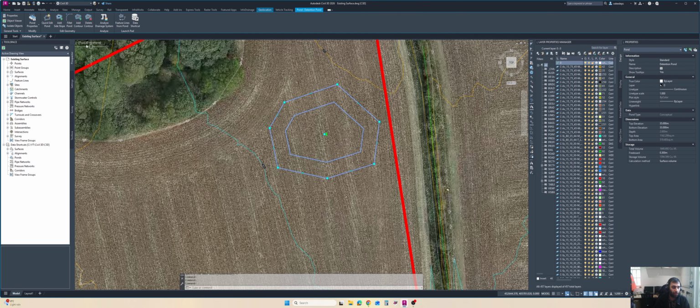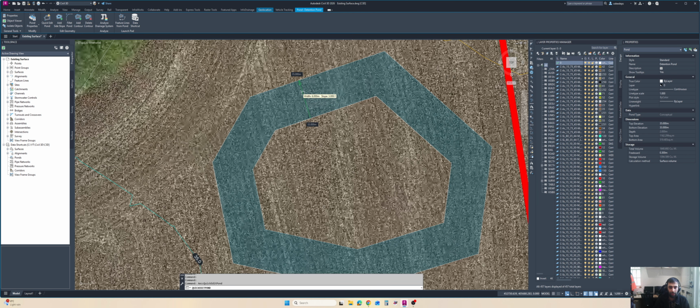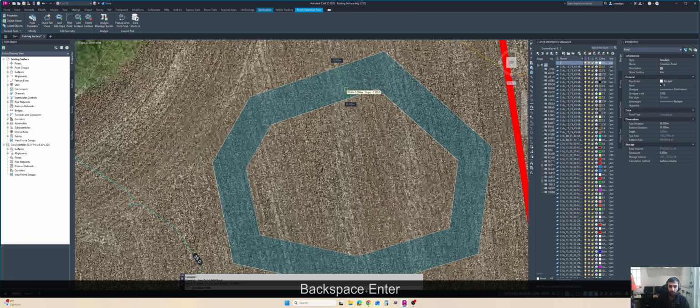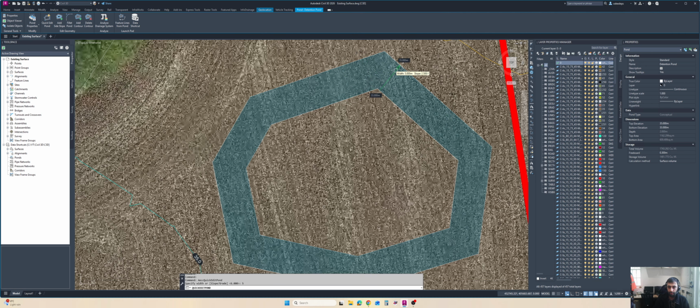And so if I go for the quick edit, we can see now it says that 35 is the top of the bank and this one is the bottom of the bank, and we can edit it as well. For example, click here, specify the width. Now it comes with the 6. For example, if I want 5, now it changes the width, and then it also has the slope as well. For example, if you see here at the bottom, you can see specify width or slope or grade, so you can select anything.